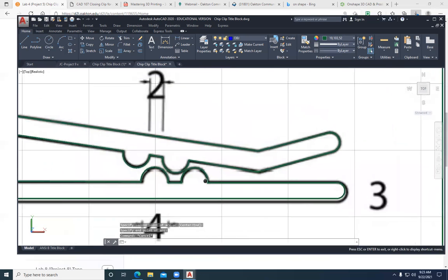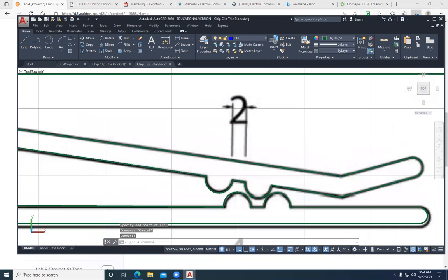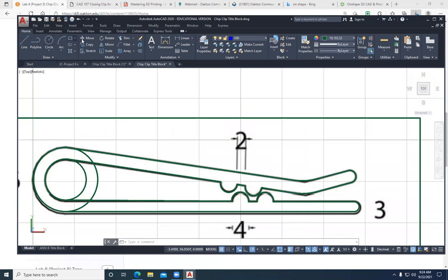Oh yeah, I was talking about softening up the radiuses because they're potential break points. And so if I put a fillet on these, and you'll get more experience with radiusing these, but I'm just going to say radius. Yeah, we'll leave it at 15, whatever was in there. And then that kind of softens it up and it relieves some of the stress points that would accumulate at a sharp corner. And you could do that with these. I would probably put it at a lower threshold, and then I'll trim this out.